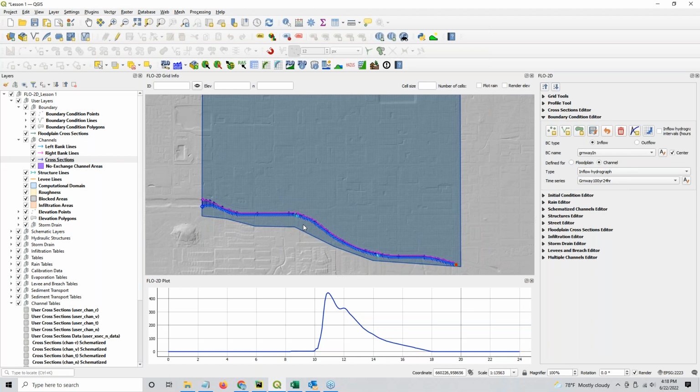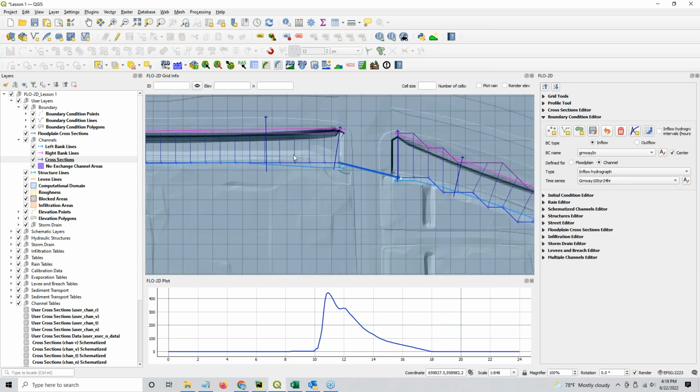If you have a backwater condition, you might see some instabilities. So you just want the grids or the time step to be a little bit slower so that it has less water to transfer to the downstream direction and it deposits it a little closer, so that the water that hits this cross section and the calculation time for it to hit inside this cross section are accurate based on the time step.